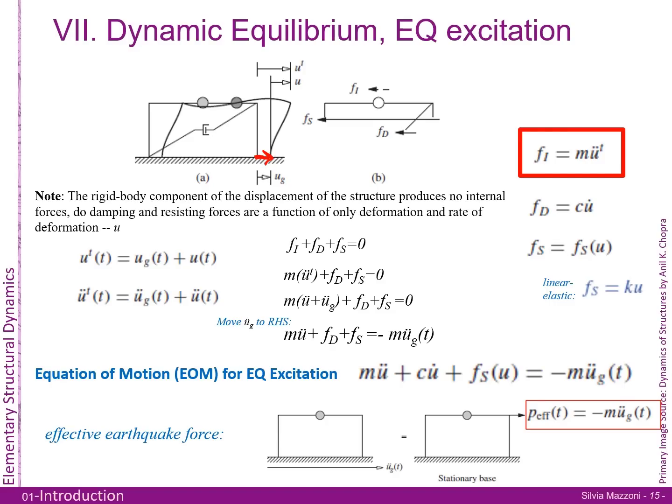It's the ground that is moving. And the ground is displacing and has a displacement, a velocity, and an acceleration. And as the ground moves, this whole thing is going to move with it. So if we have a rigid system, so if this is our original model, okay, and we have a rigid block and the ground moves, the block is just going to move with the ground and not respond, okay?